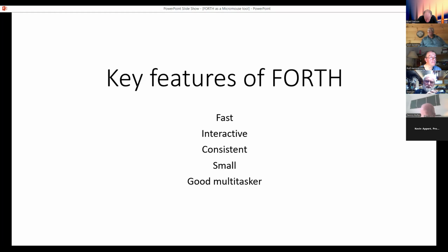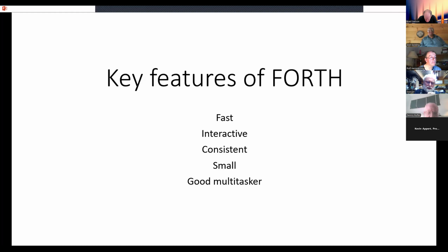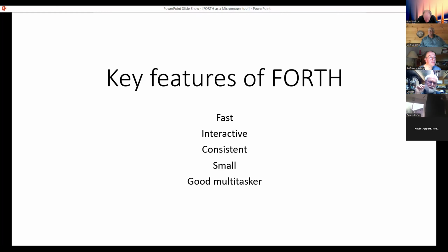Small footprint for the software helps with the choice of microcontroller. The chips with more memory tend to come in physically larger packages. As you can build a mouse with as few as 20 pins on the microcontroller, you want the option of using small controller packages. I can fit any of the mouse events in 64K of flash on a 32-bit processor. And for a following device, something that doesn't need the solver in it, 16 kilobytes on a 16-bit processor is sufficient.